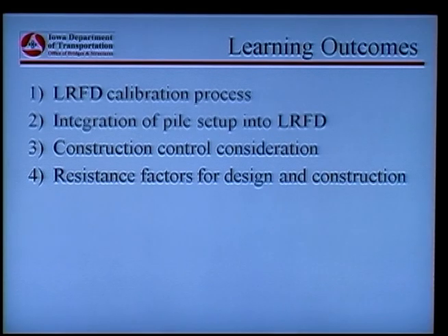So what we're going to learn from this presentation is the LRFD calibration process, how we come up with those numbers, how we could integrate the power setup into the LRFD, construction control consideration, and the recommended resistance factors that we develop and come up with for design as well as for construction.